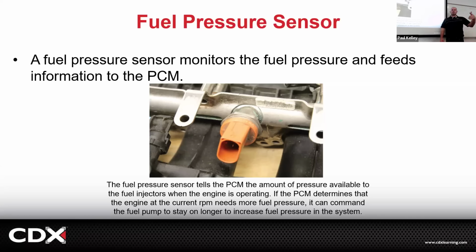So if you wanted to check fuel pressure on a Honda, Toyota, Subaru, most Mazdas, the new Mazdas, not the old Mazdas, you actually have to disconnect the fuel line, put in a T, reconnect the T to the fuel rail, reconnect the fuel line to the T, and then your gauge would attach to the T, and then you could check it. But by then you've spent a bunch of time and adapters and goofing around. It's really irritating. So you get no fuel pressure test point, and you get no fuel pressure sensor. You've got to use T's and adapters and stuff. It's pretty irritating. Okay. Whew, I'm done.